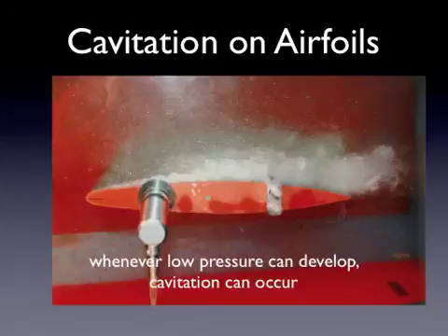So when you see cavitation in problems, just remember you have to compare the actual water pressure in absolute terms to the vapor pressure of the fluid, and if the absolute pressure is below the vapor pressure, you will get cavitation.